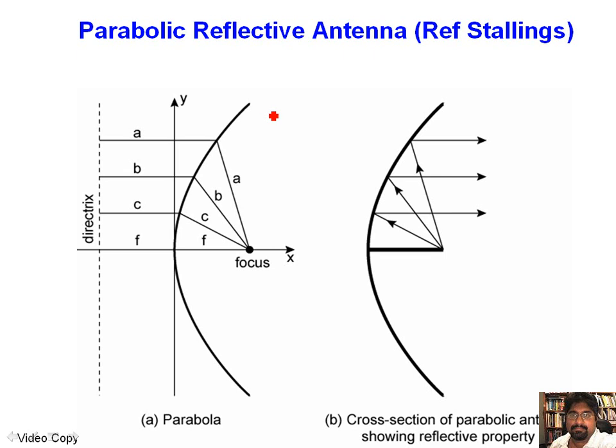That's true. The other thing that you will notice is, because of the equation that's associated with the surface of the parabola, if you put a source here, the wave that is produced by a parabola will be planar. That means it will produce almost perfect wave fronts at which all the points on that wave will be in phase. So effectively, what that means mathematically is if you were to draw a line here, and if you were to look at this path length here, and this path length here, and this path length here, they'll all be equal.